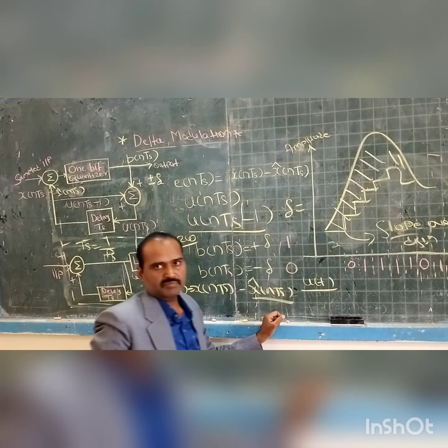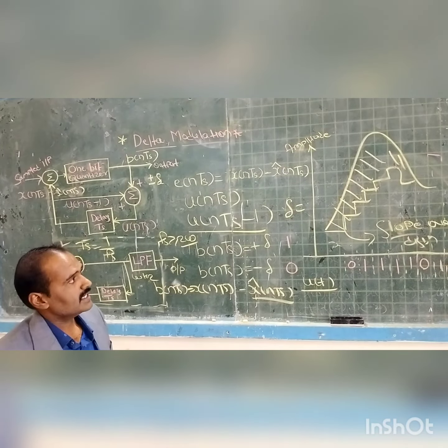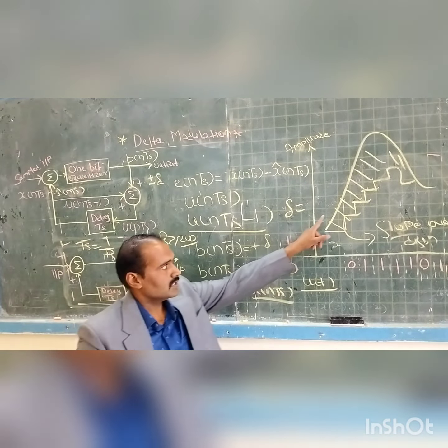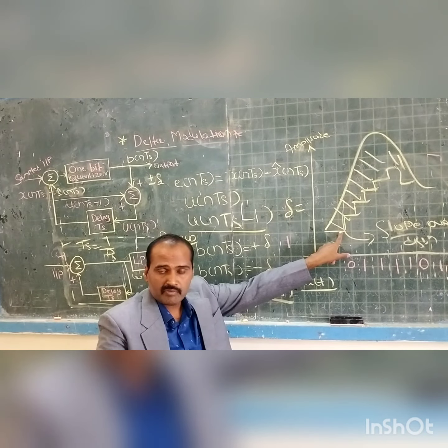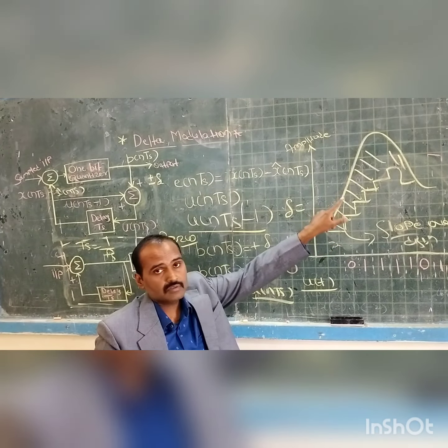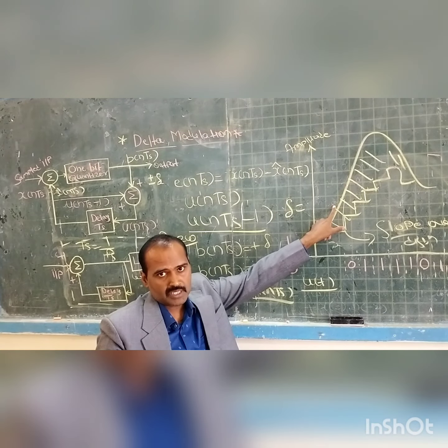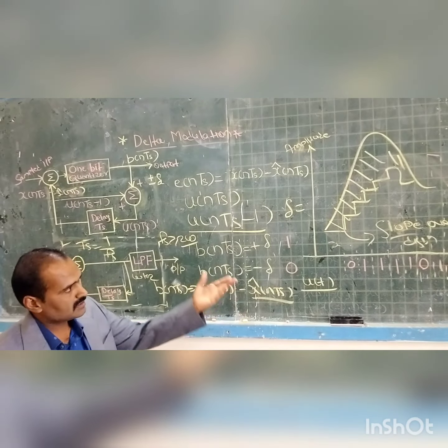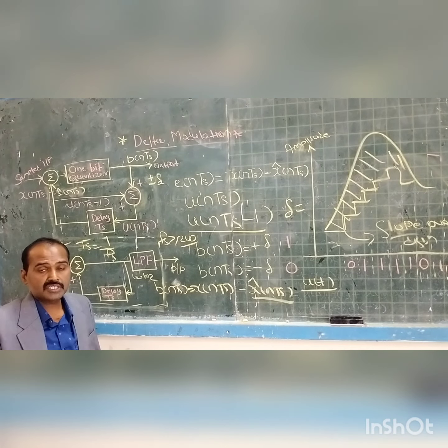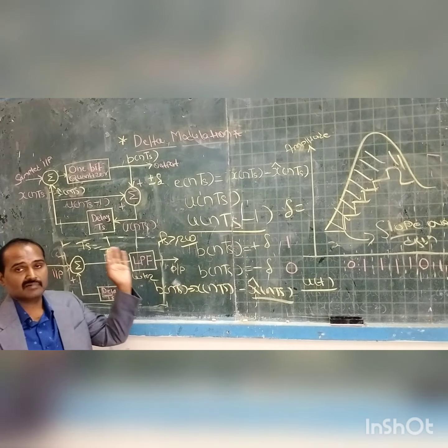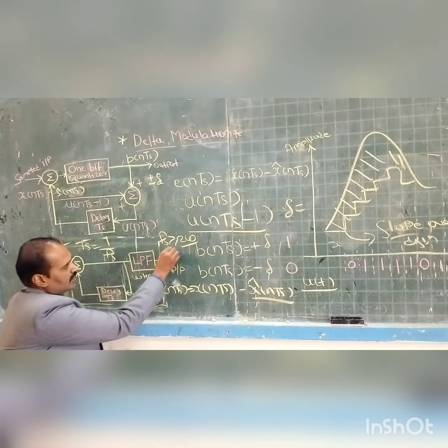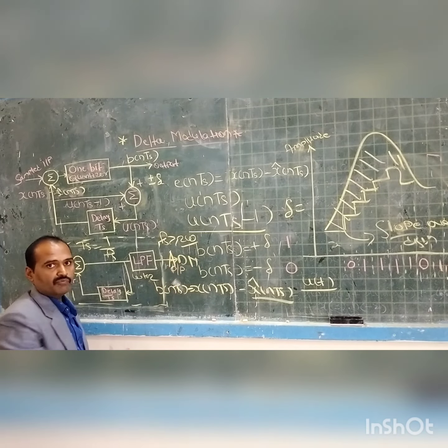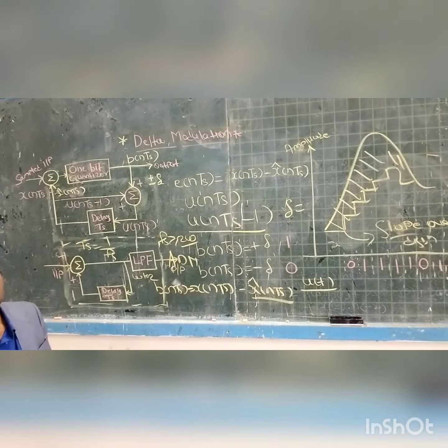This is the major disadvantage of this delta modulation scheme. Practically, the slope of the continuous time signal can be very high. At that time, the step signal falls behind and cannot strictly follow the envelope of the continuous time signal. Such distortion is called slope overload distortion. To overcome this disadvantage, we use another enhanced pulse modulation scheme, namely adaptive delta modulation. Hopefully in the next session we will discuss this scheme.